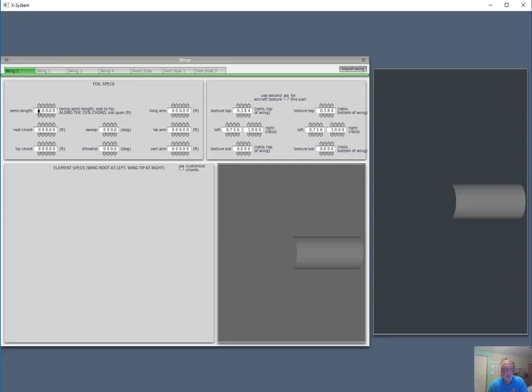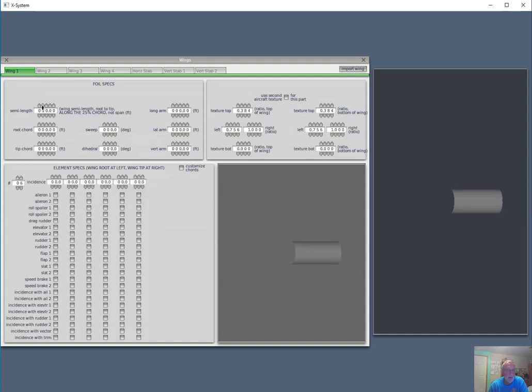This is where we're going to create our wing. The semi-length is along the 25% chord, so the handout shows you how to calculate this based on the b/2 value. We're going to put in a value that's calculated of 23.38.